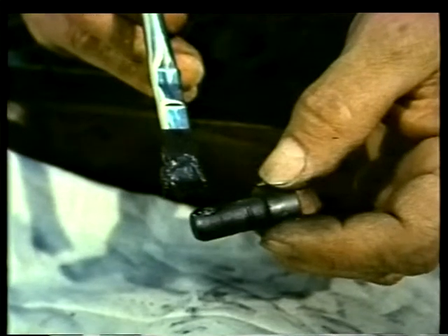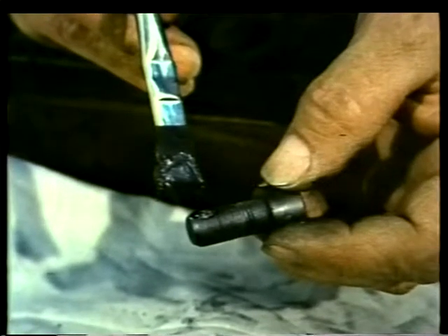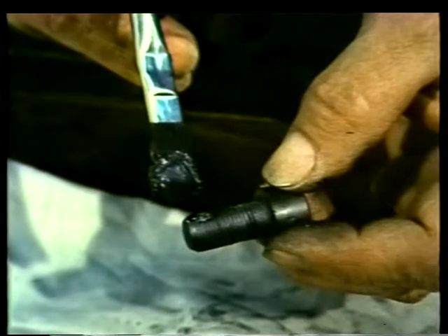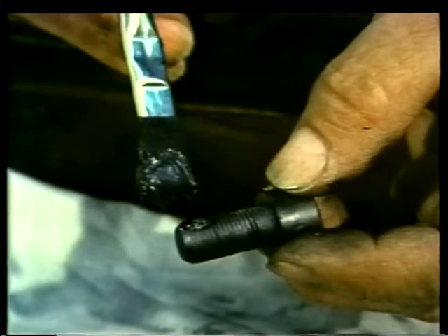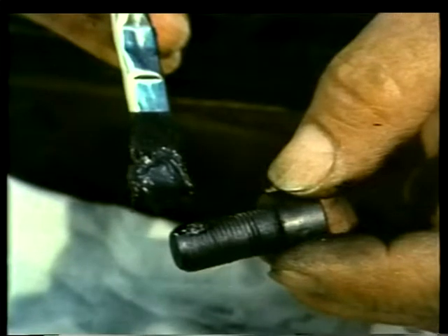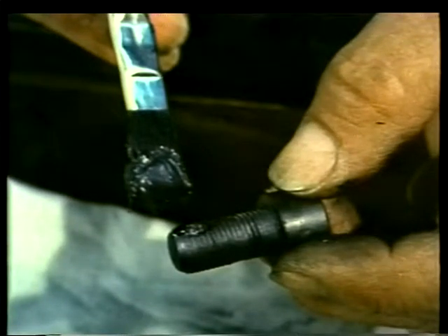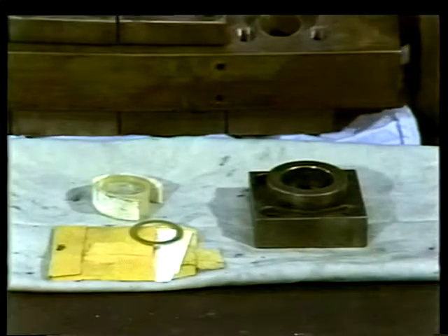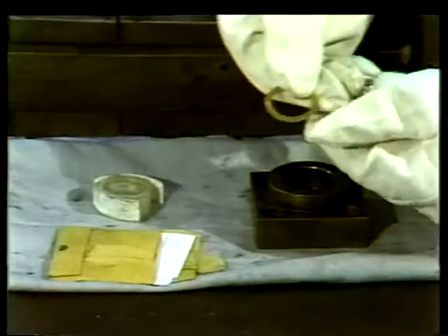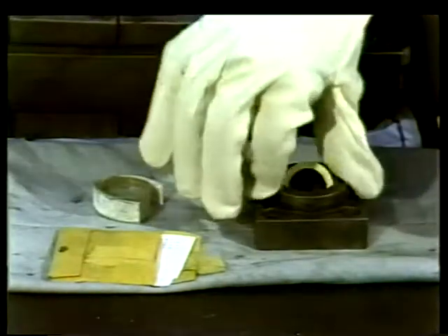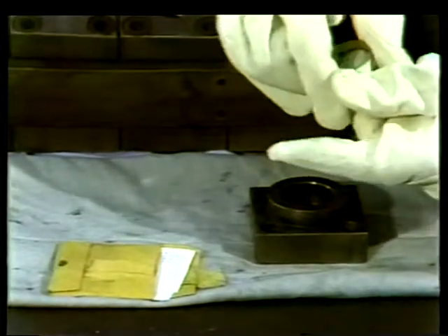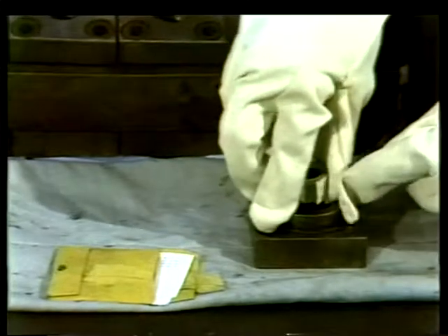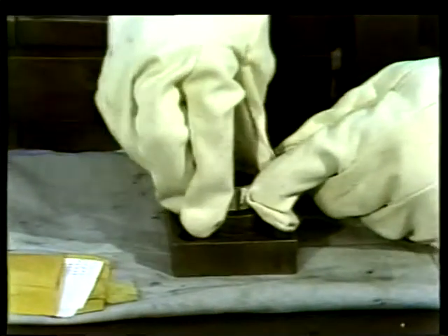Lubricate the threads and bearing surfaces of all the cap screw heads with Molykote or another high temperature lubricant. This will make the cap screws easier to remove the next time the gauge must be disassembled. Put a new cushion gasket back into the cover plate. Wrap the packing strip around the outside of the glass and put it on top of the gasket. An effective way to avoid damaging the glass is to wear clean gloves during reassembly.